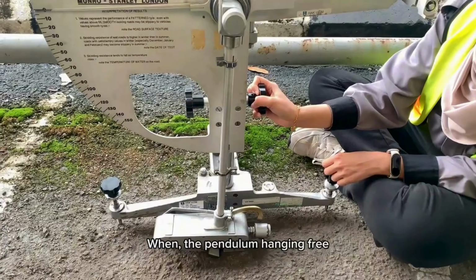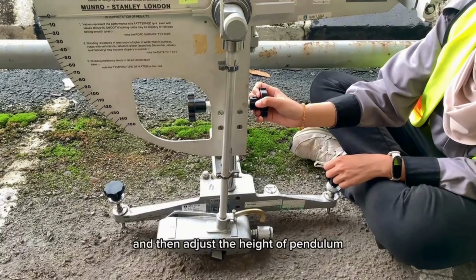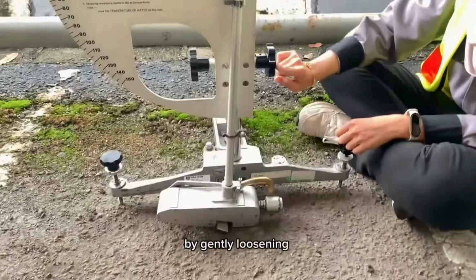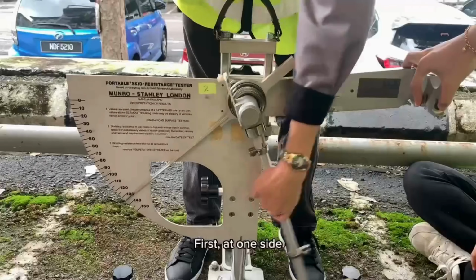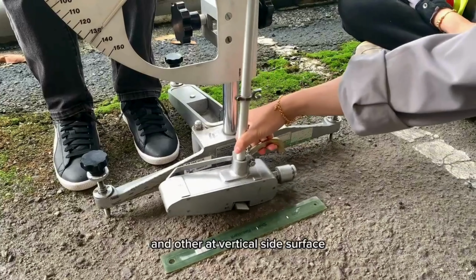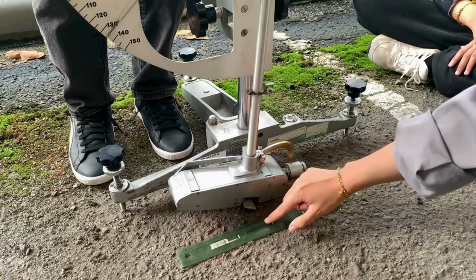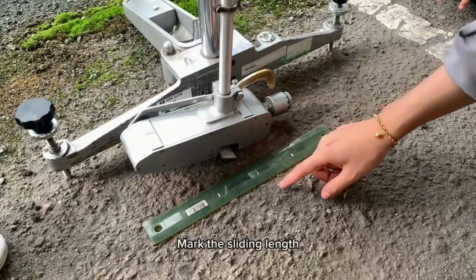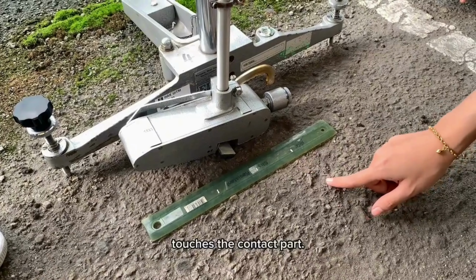When the pendulum is hanging free, place the pendulum at the contact pavement surface and then adjust the height of the pendulum by gently loosening the arm until the slider of the pendulum touches the pavement surface, first at one side and then at the vertical side surface. Mark the sliding length of the distance between 2 points where the slider of the pendulum touches the contact part.